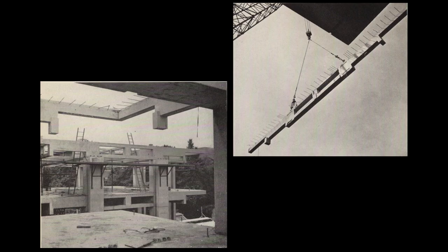Okay, so they're pre-stressed, and then once they're at the site, they're post-tensioned, which means that all of those reinforcing rods, whether they're running the length of the particular joist or whether they've been fed through horizontally, are all going to get connected and pulled taut into a system that expands in 2 dimensions and that forms the joist system that supports the floor, which is going to be above.